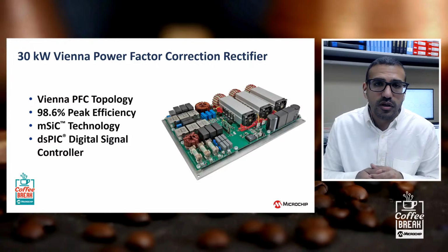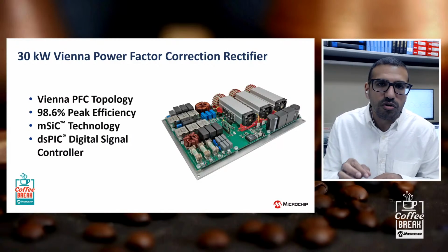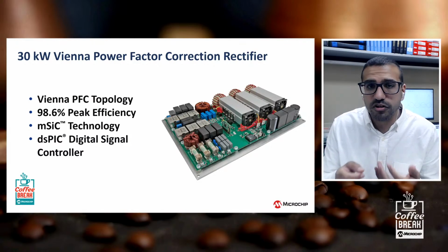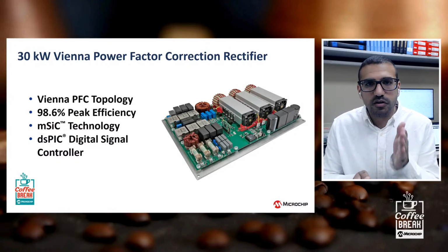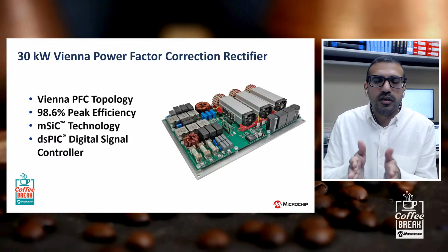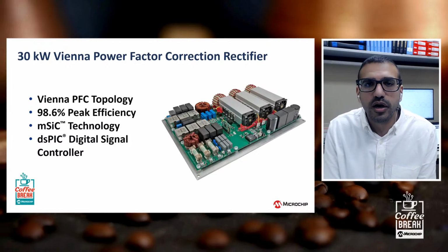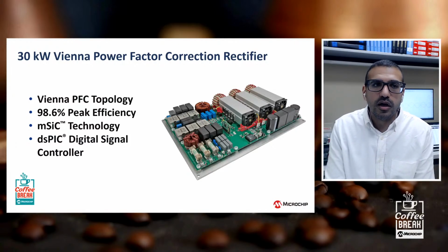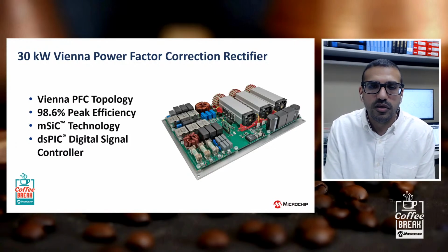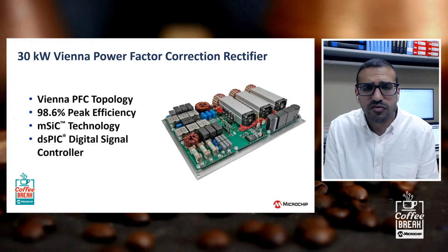We also have a very low thermal resistance for the thermal interface material. Between the case of the MOSFET and the heatsink, we use an aluminum nitride insulator and phase change material, and that really helps decrease the maximum junction temperature of the MOSFET, and that's what's enabling this high efficiency.